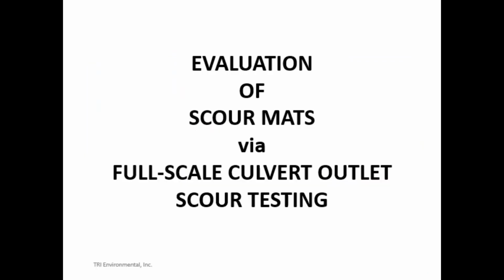High-energy applications like culvert outlets not only require special anchorage, but they also require a special assessment of the TRM's ability to resist the unique scour forces encountered. Unique large-scale tests have been developed to make these evaluations.